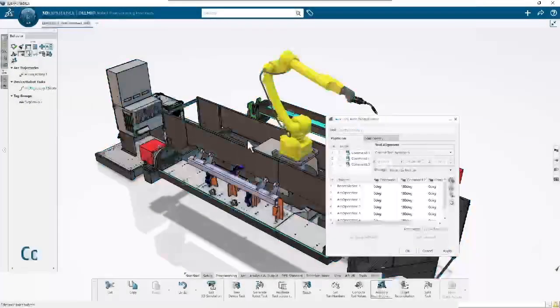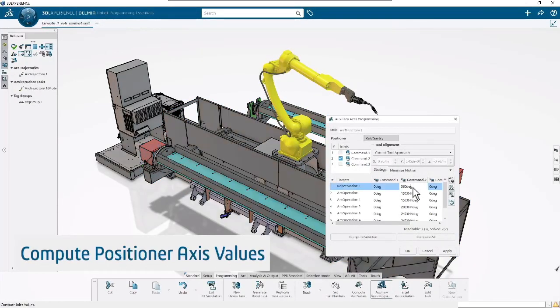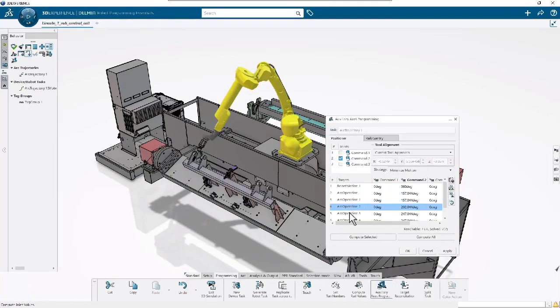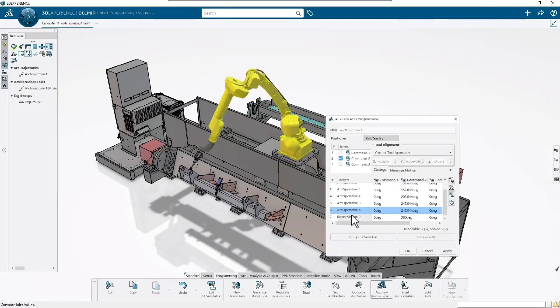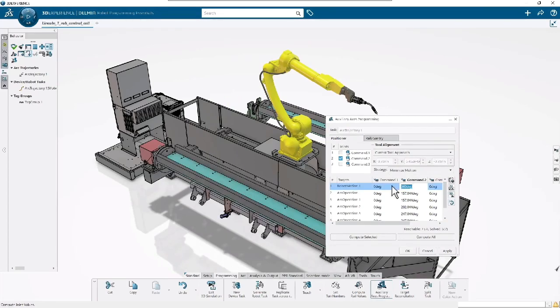And then I have a nice workpiece positioner that allows me to update automatically. So I'm using the auxiliary axis programming, which is activated over there on the left. And I can set parameters based on how I want the robot to move. So generally, I like minimized motion. It keeps things from crashing. And I want to make sure that it starts with the workpiece up.